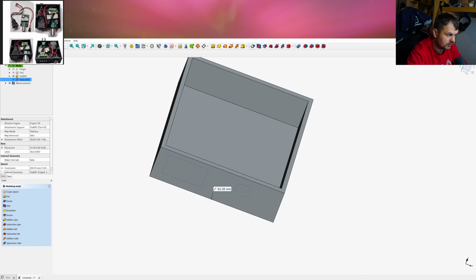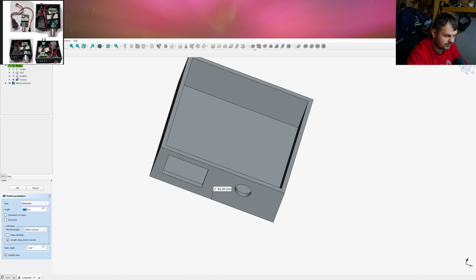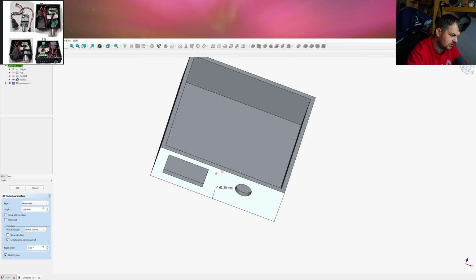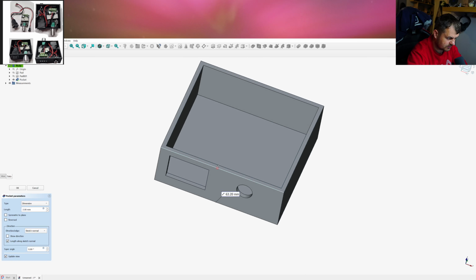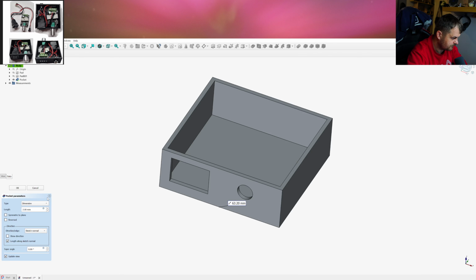this sketch we want to have a path. We can do hole, but I use pocket because it's just easier. We don't need different features than just a dip. So it needs to be at least 2 millimeters deep because our wall is 2 millimeters. Yep.